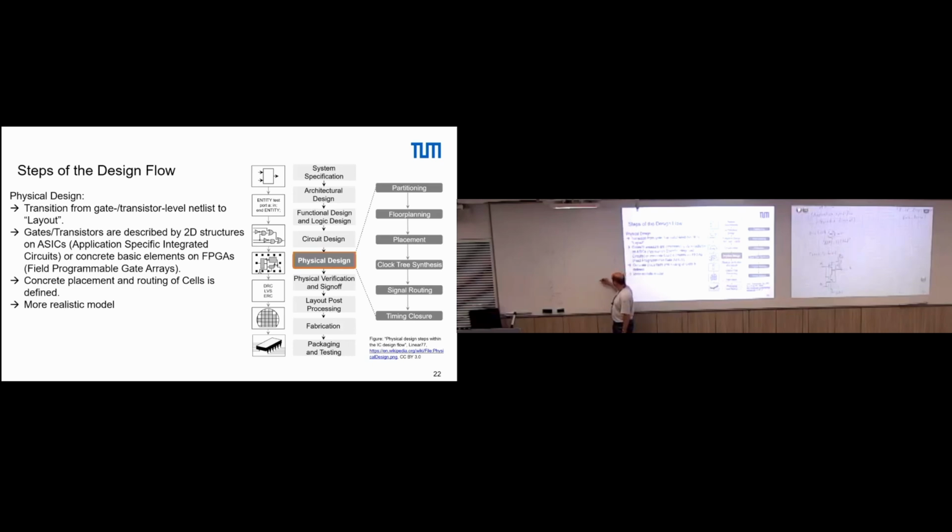So you have p-dopant base material, and you implement here, it depends a little bit on the technology how this precisely looks, but generally you have something like this. You have here some n-dopant, and here some n-dopant connection, commonly known as drain and source. Then you have to put some oxide on top of this, right?